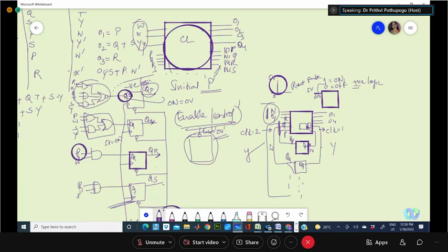And see here, R you have here and here. At this state of R, when this is getting updated for the next clock, that R condition along with X is evaluated. When the present state is R and X is true, it will go to the next state of P, else it will go to the next state of S. That means there is always one next state transition condition available for us.